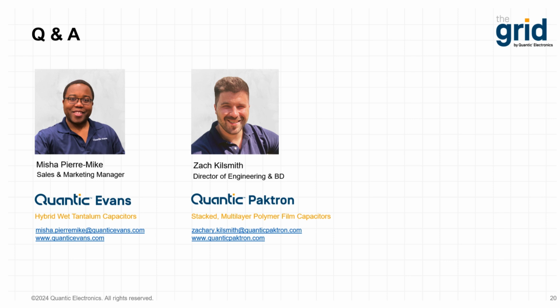MLCCs are becoming increasingly more reliable and more favorable for mid voltage, mid cap applications, 35 volts to 100 volts, where they were previously not really considered in high reliability. That was once a place held firmly by film capacitors.